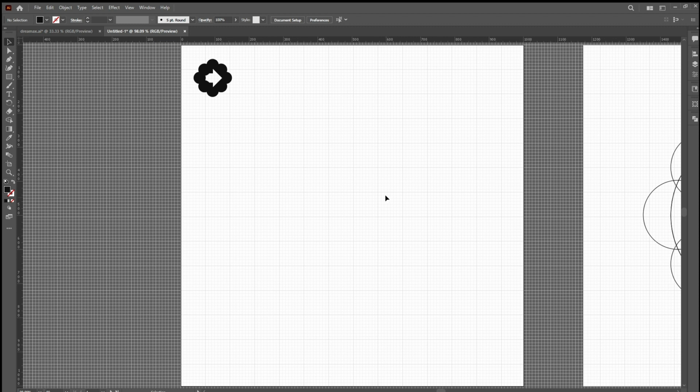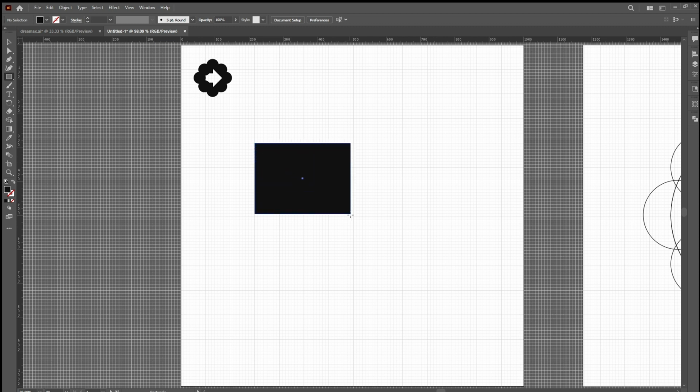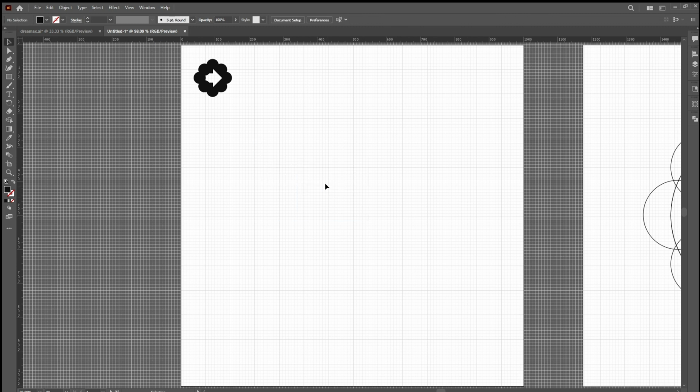All right, so the second thing you need to do is actually go to view. Once you come to view, go to guides, and sorry, not guides, snap to grid. So do that. This is so that whatever you draw would snap to the grid. Like if I'm drawing let's say a box, it's following the grid. You can see what's happening. It's taking it one step at a time. So this helps me position things in a way that they'll be well calculated.